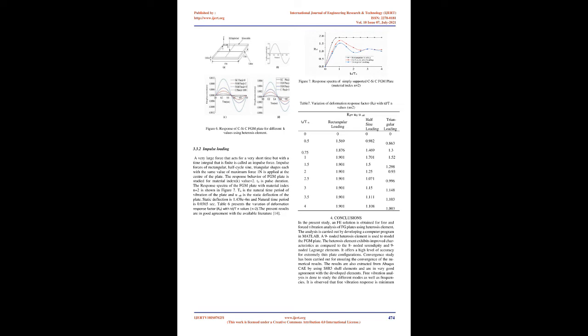Table 5 compares the undamped and damped cases. Figure 6(c) is for a simply supported plate. The maximum displacement at the center of the fixed plate, as shown in Figure 6(d), is less than that of the simply supported plate. Figure 6 shows that the maximum displacement at the center of the plate increases with the material index, n value.